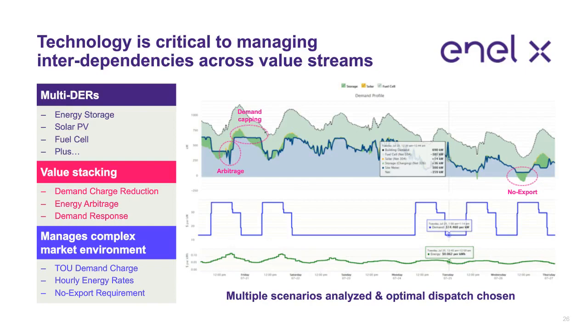It's taking advantage, it knows what value exists at a given point in time. So those are the two graphs on the bottom, showing how valuable a dollar per kW and dollar per kWh is across the day. And so you can see highlighted here certain times where the software is recognizing the value of what the grid is offering and doing energy market arbitrage, demand charge management, while also incorporating other on-site requirements like export constraints.